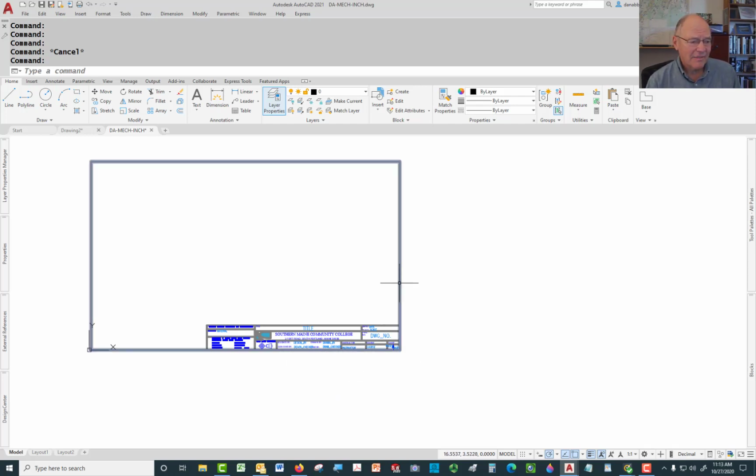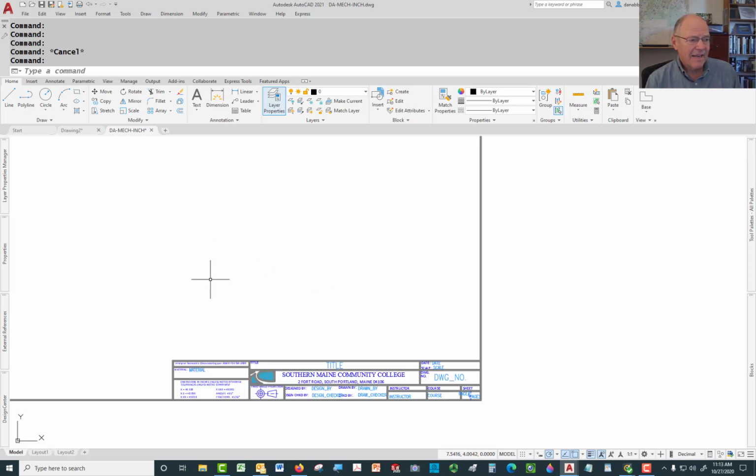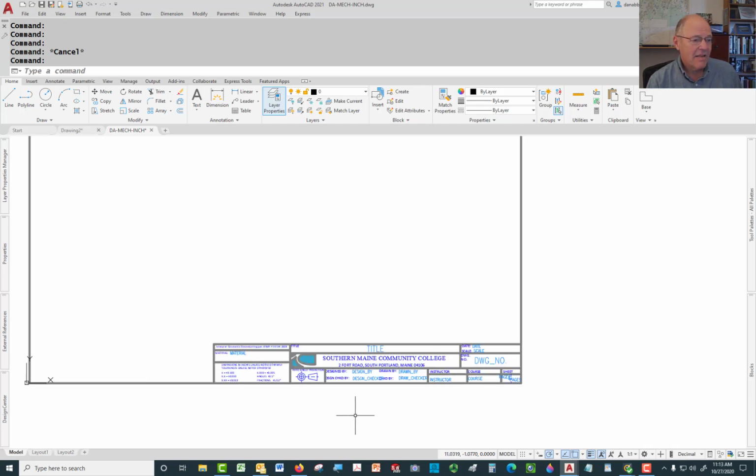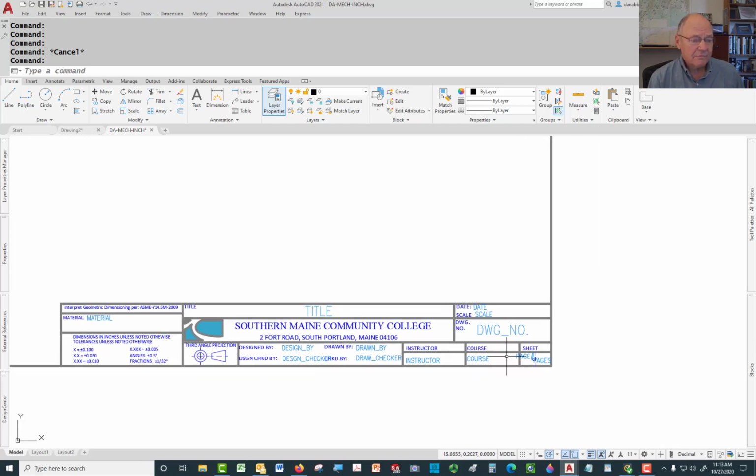Many title blocks are a little bigger than this. They come up higher. But when I'm using mechanical drawings, especially for A size and B size, I want a relatively low profile title block. So I don't want a title block that kind of comes up here like that. So this is really what I would want. And if I were to put some dimensions on here, we'll do a Q dim, and I'll just show you where I'm picking all these lines here, my Q dim.